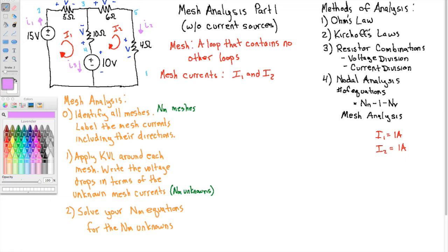Well, to answer this, first notice that I1, the mesh current, capital I1, is the only mesh current of the 2 that's contributing to this branch. Okay, that must mean then that branch current I1 is equal to mesh current I1, 1 amp. There has to be 1 amp going up, because that's what capital I1 was, and capital I1 is the only thing contributing to this branch.